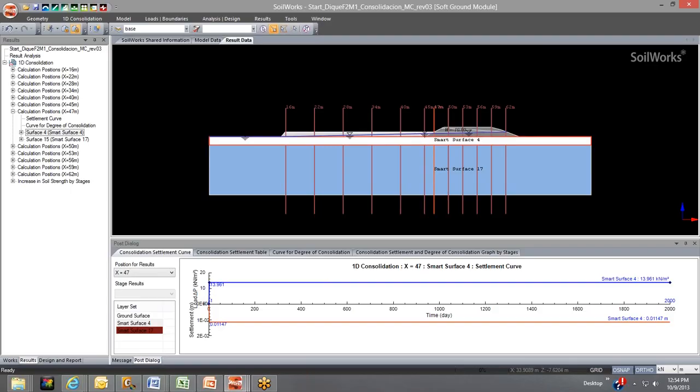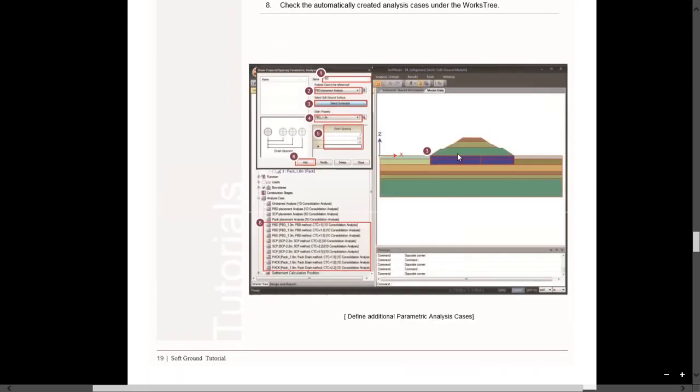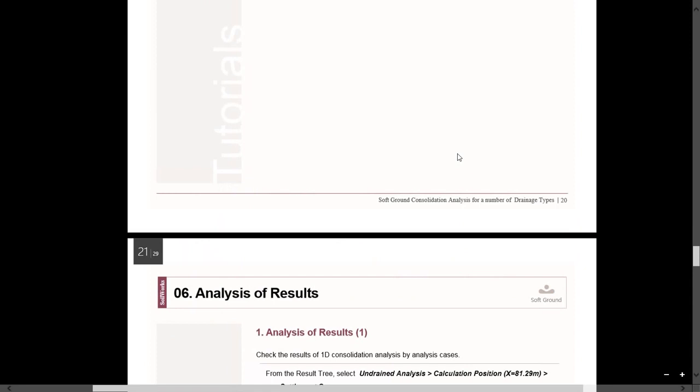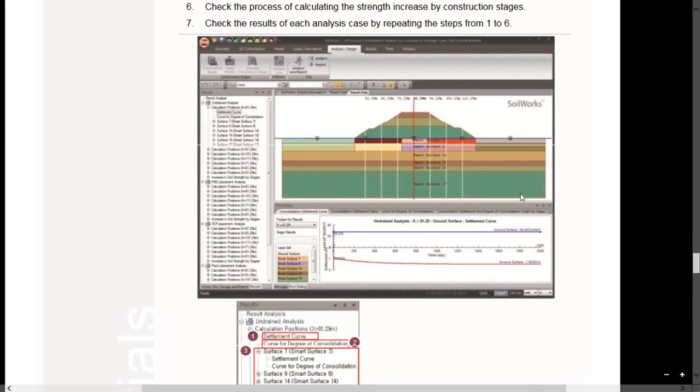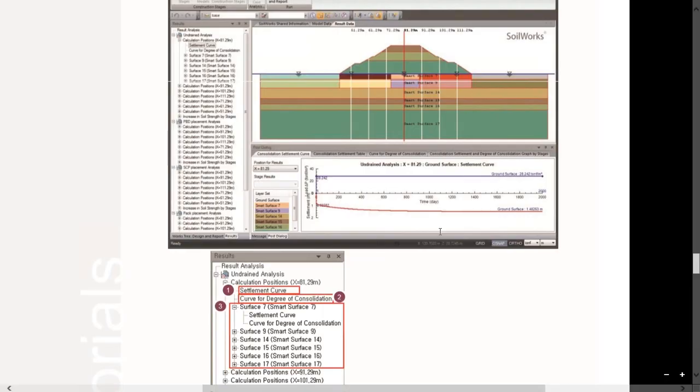But let's say, for example, and I have a tutorial here, which I'll give you a copy of. These are just screenshots from the completed project. Let's say you have a project with some consolidation which isn't so linear. As you can see, for this particular project, there is a certain amount of consolidation. So here it'll give you your primary consolidation or your immediate settlement, and then over a period of time, this was 2,000 days, so maybe 6 years later, the total settlement will be doubled, about by 1.48. So once I send you the tutorial, I'll send you a copy of the completed model file as well. So maybe you can compare and contrast it